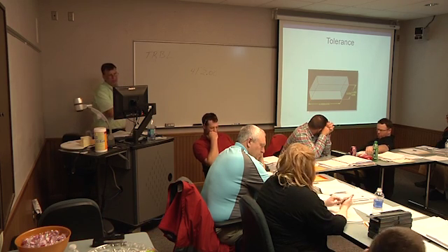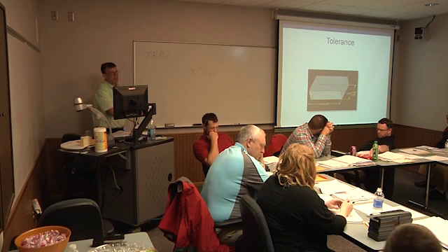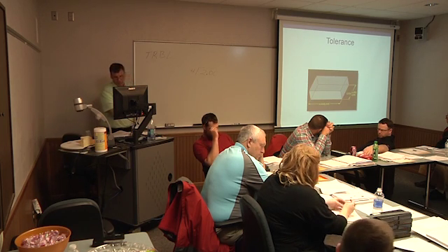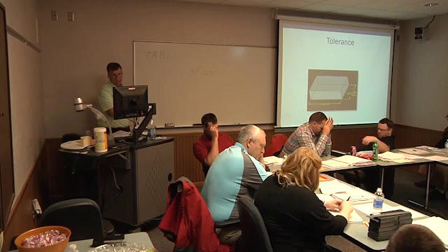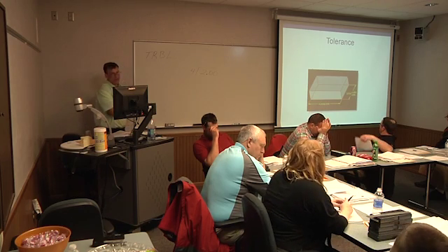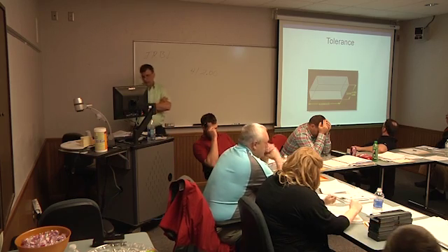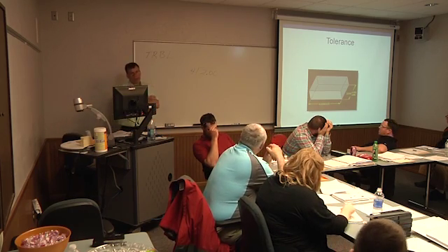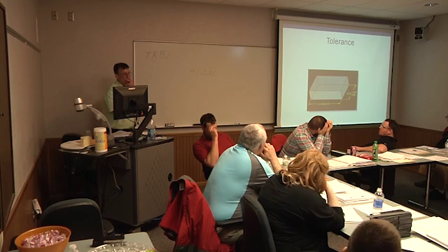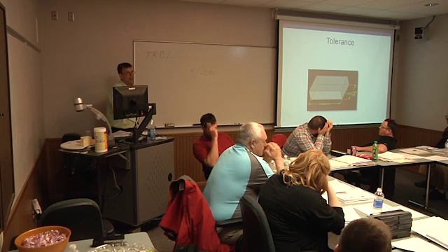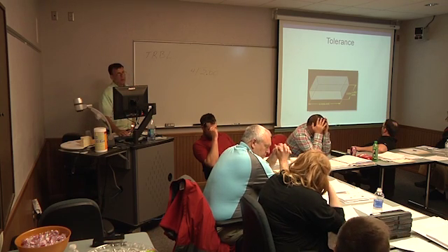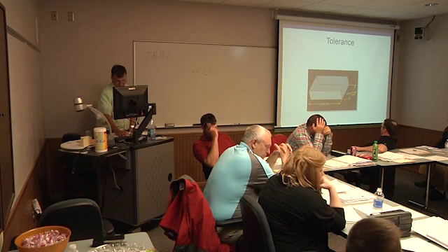Is that within tolerance? Given the tolerances, it's plus or minus 0.005 of an inch, but the actual width is 4 6/1000. Would that be within the tolerances? No, not if your tolerances are plus or minus 5/1000. So it's good for students to understand the concept of tolerances and what is acceptable and what is not.